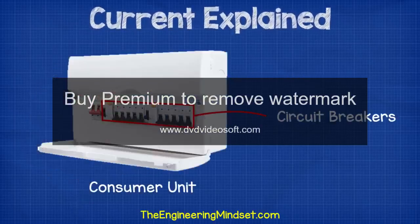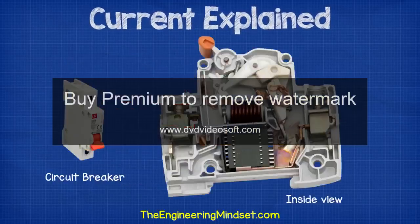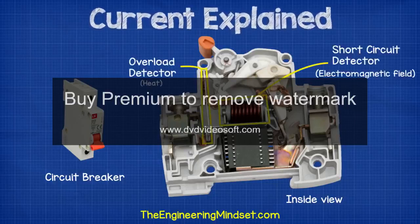Another device we use, and you've probably seen these in your homes, this is the circuit breaker. It's essentially a switch that will automatically open to break the circuit if it detects too much current or too many electrons flowing through it. It's rated to handle a certain amount of electrons flowing through it per second, but it measures this using heat or an electromagnetic field to detect and act on if too many electrons are passing through it. If it exceeds this, then it will open to break the circuit.